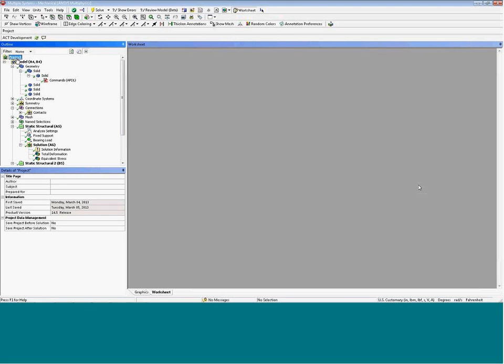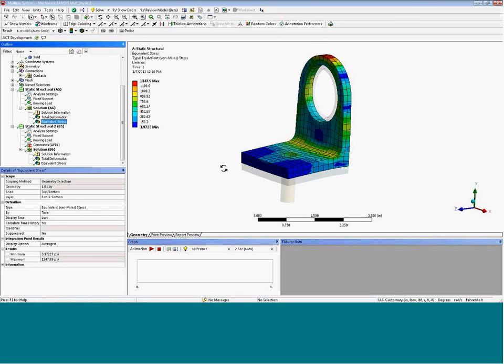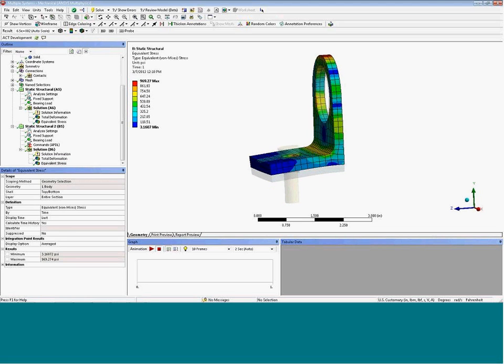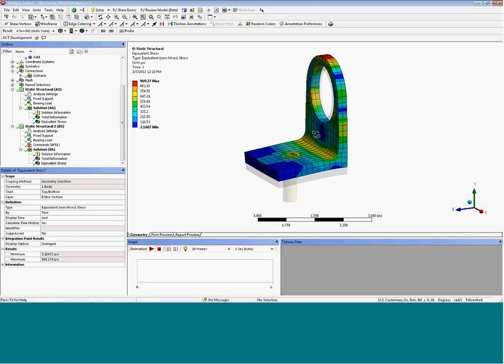So this model's finished. If I go back and look at what happened here, this was the original analysis. There's a stress on this fill block portion, like 1350 psi, and then look at the stress on this next part, and it's about 1,000. So we can see that did change the material and change the stress. So that block did work.